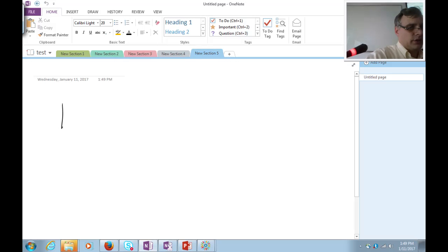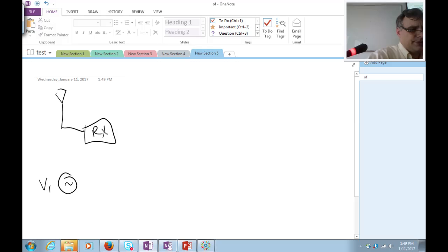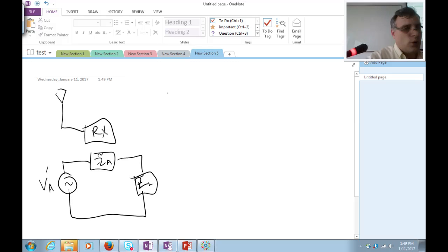What about at the receiver? Well, here, recall that I said this looks like a V_A prime, some sort of complex antenna impedance Z_A, and it connects to a complex load Z_L. Once again, I'm going to break Z_L out. The real part I'll call R_L. The reactive part I'll call X_L.